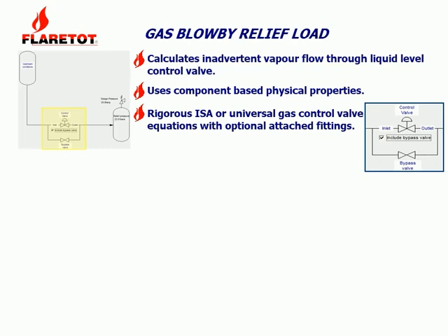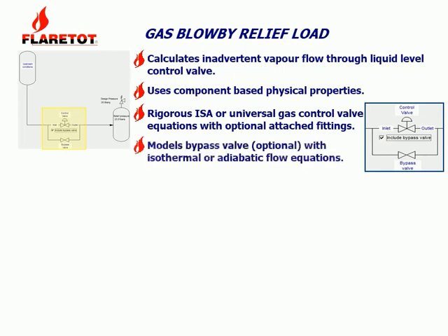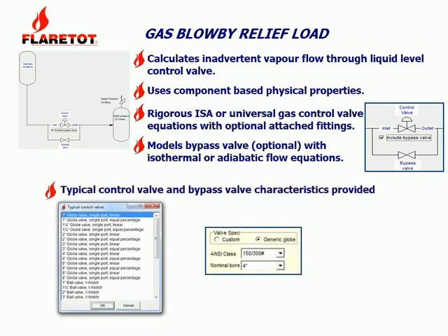Fittings attached to the control valve can be included. A control valve bypass valve can be included. This can be modeled with isothermal or adiabatic gas flow equations. A database of typical control valve and bypass valve characteristics helps provide estimates during preliminary design.